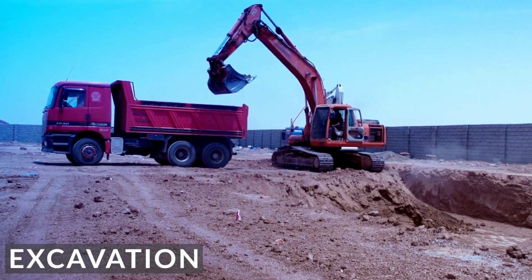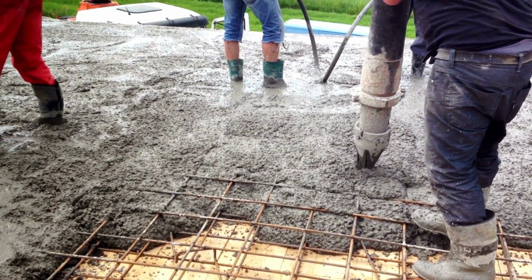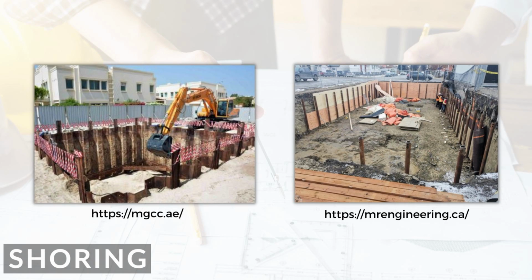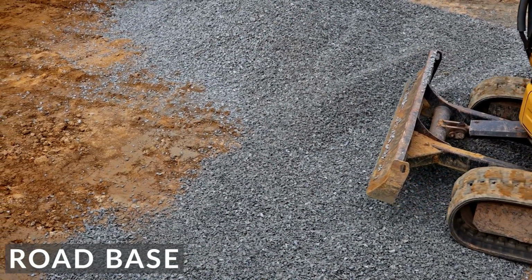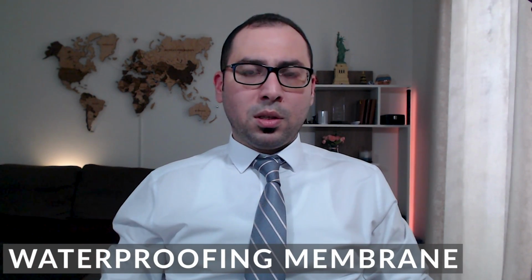Of course, the volume will increase, and also foundation and concrete steel will increase because you will have a raft instead of isolated footings, for example. And then you might need shoring also, depending on the excavation level. You might need dewatering as well, depending on the groundwater table. You might need 1 or 2 layers of road base below the raft to reduce the uplift pressure, and you might need substructure waterproofing of membrane instead of just normal cold applied bitumen or something. So all of these are things that will impact the site and the concrete works in the project. So having a basement will have a major cost impact, so we have to be careful about this.